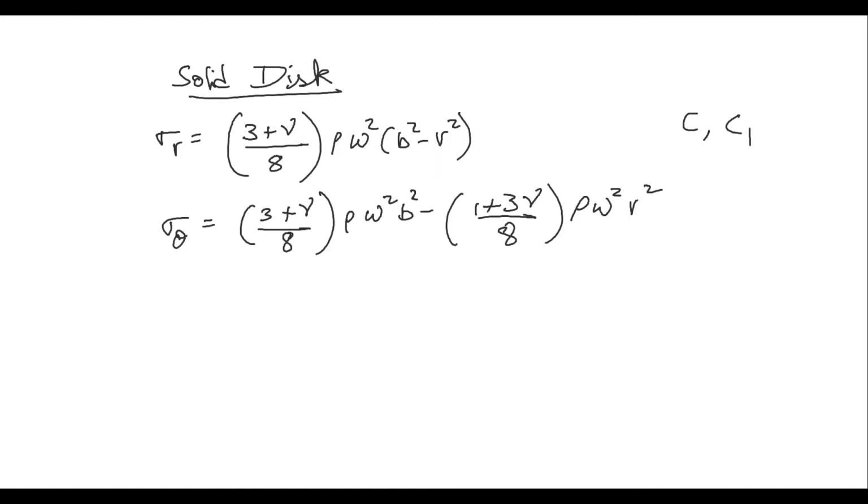Okay, so in this case, you can calculate the state of stresses for a circular disk using these formulas, sigma r and sigma theta. When r equals 0, this term will become 0, because you have r over here. If it is 0, then automatically it will become 0.